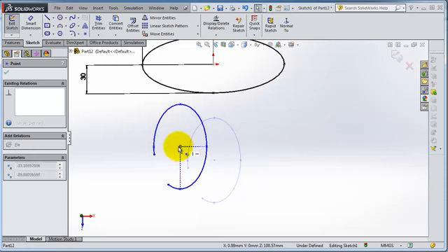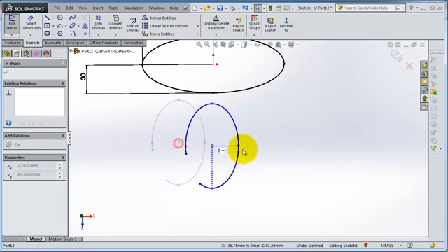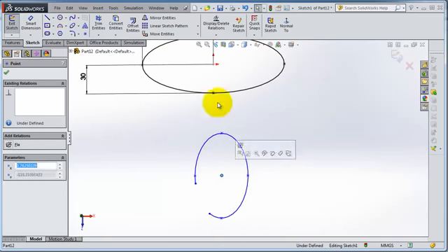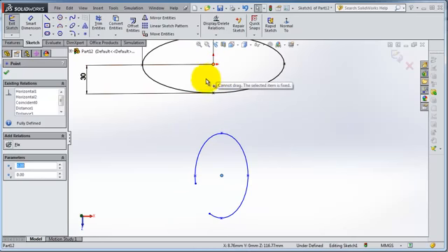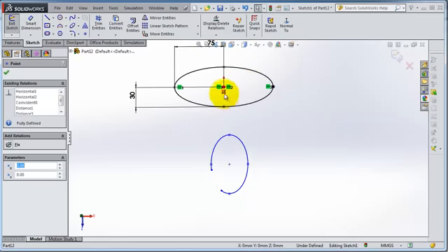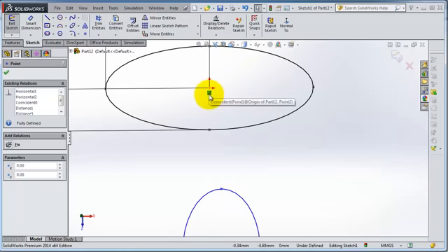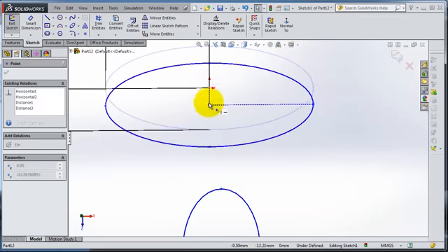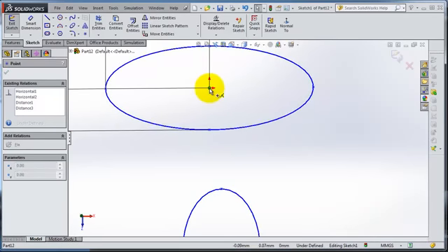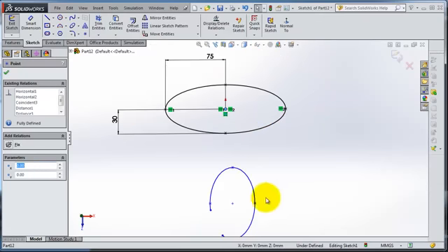So you are able to move your sketch if you click on that, but in this ellipse you are not able to move it because you have a midpoint and the horizontal, or you have this intersection relation, coincident with the origin. If you click that and delete it, your sketch ellipse is undefined and you are able to move it. So let's move it again and add origin, and you notice that the relation is activated.